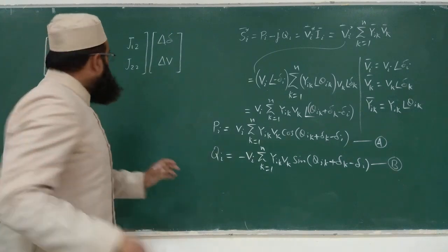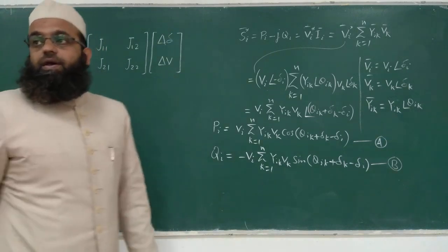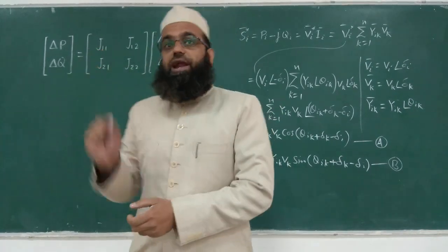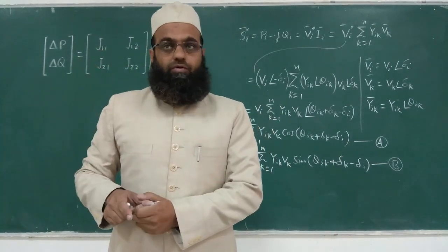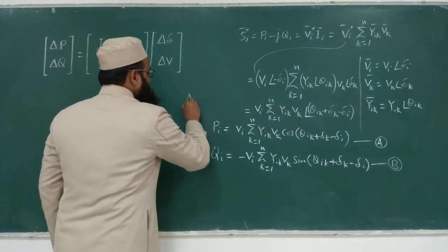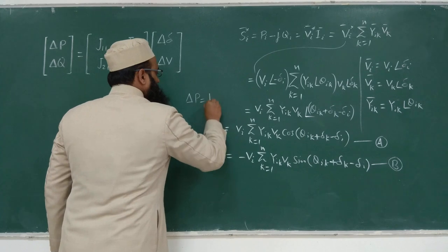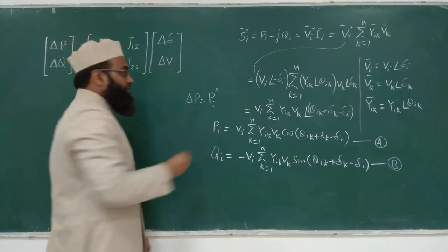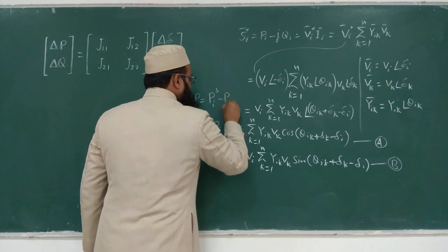So we are going to solve this so that once the solution is reached, the value of this, del P or del Q, will be nearly equal to 0, is it not? So del P is nothing but Pi specified, this is a fixed constant, right? Minus this Pi.